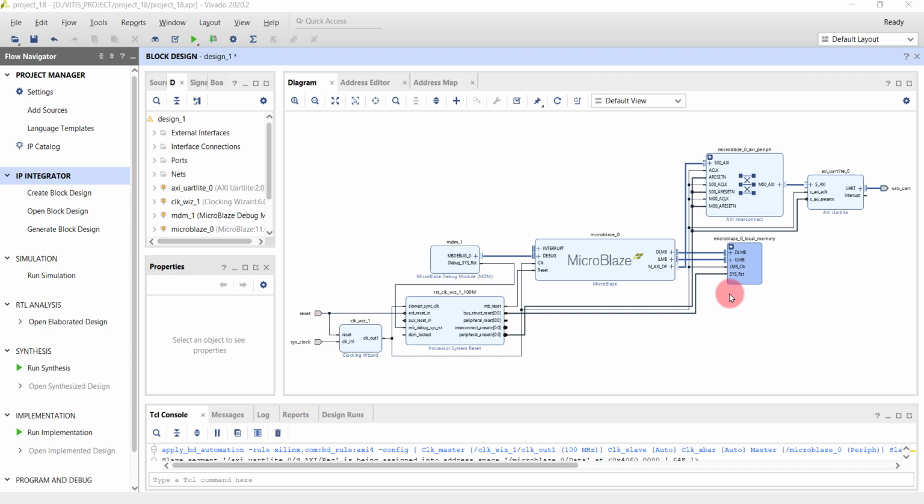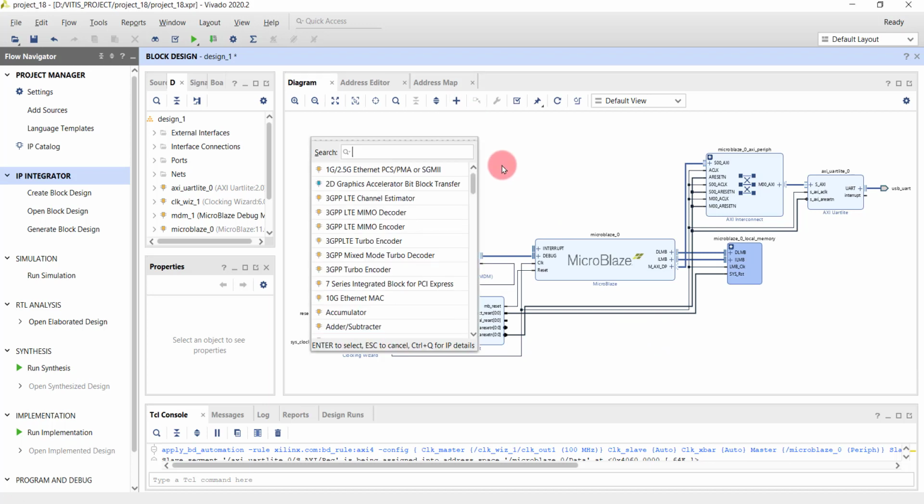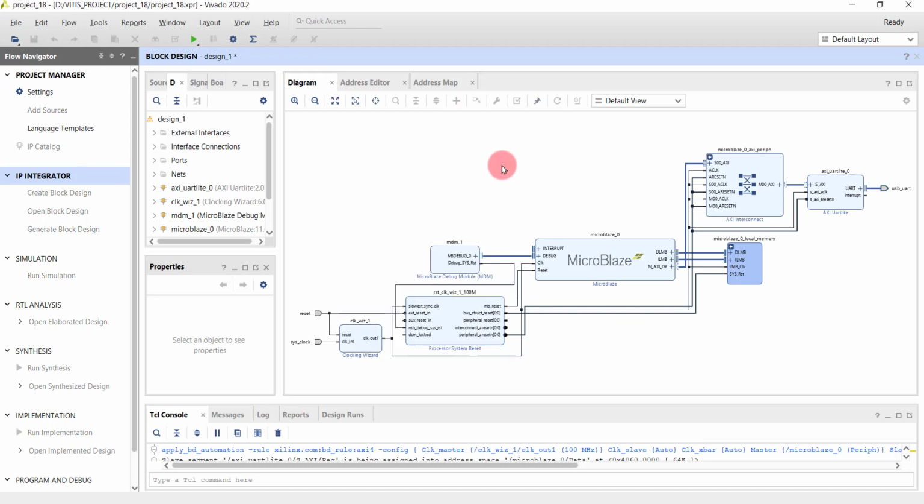on an ILA, right? So we started a new project and we already utilized the TCL script to create the fundamental block design that we've been using from the beginning of the course, right? Now what we're going to do is understand the transactions that are happening within the GPIO IP, and we will be analyzing them in an ILA window, right? So we go ahead and add a GPIO IP. This is the first step that we do.